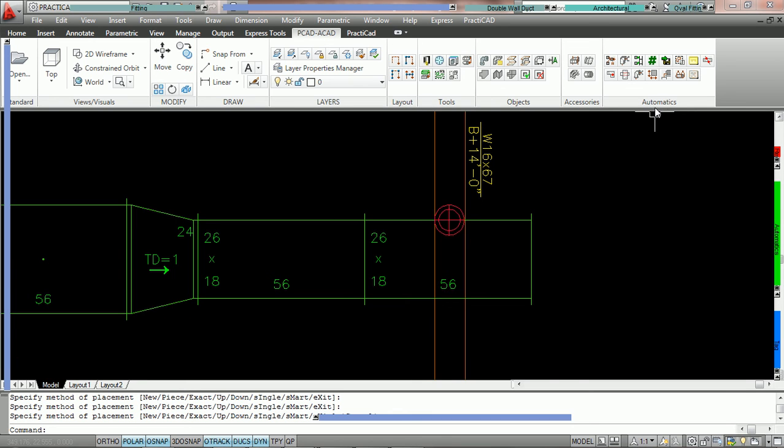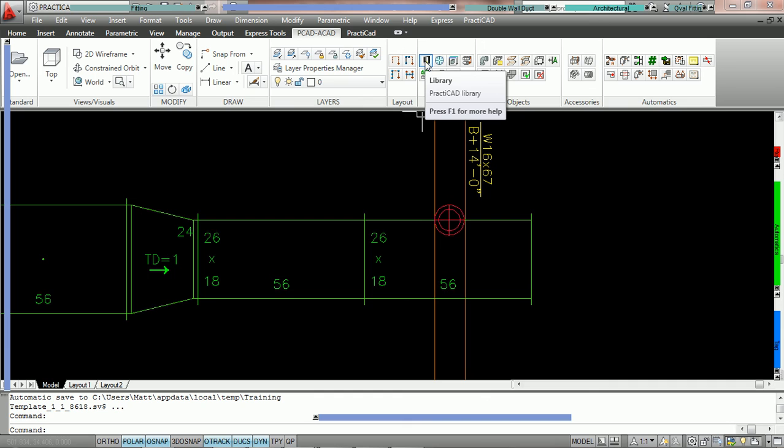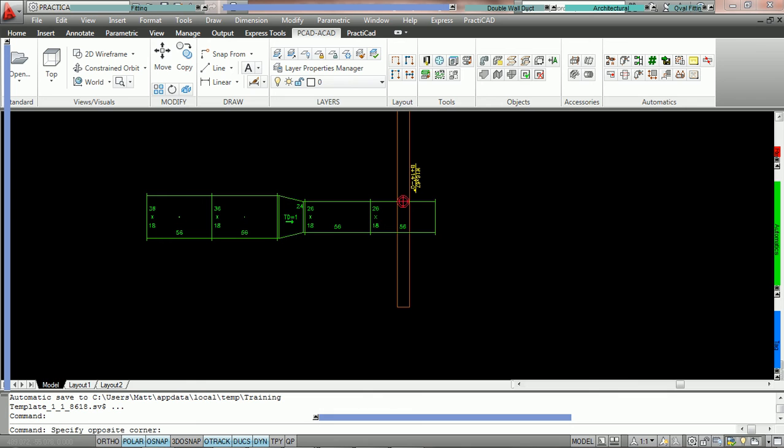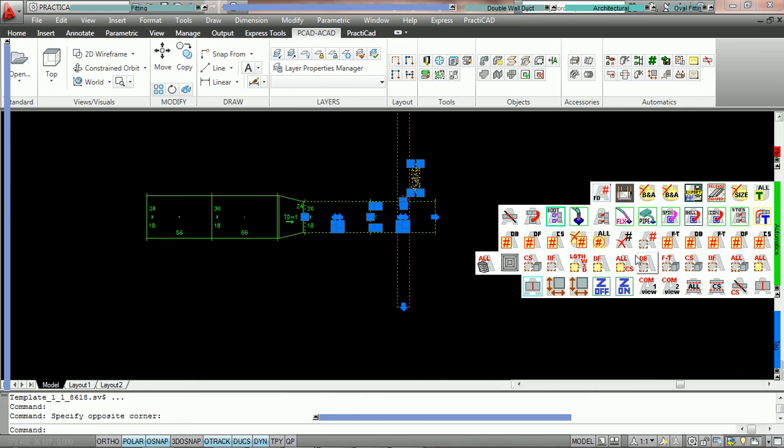So what you've decided to use in your auto collision automatic is still going to take part whenever you're drawing with the ductwork option on. So it's your choice to keep it on or off. Usually the reason you might turn it off would be the size of the drawing or your computer. Sometimes if you have a massive amount of collisions, it could slow down the system. So some users prefer to just highlight an area and run an automatic. But it is up to the individual user.